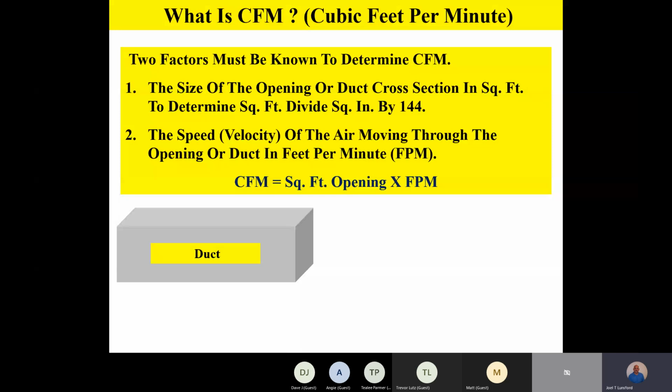A good way to do it is to have a manual damper on each. That way you can balance the airflow very nicely into each conditioned space. As you condition that space and commission the duct system, you can put the recommended CFM into each space, based on your airflow requirement. So on your branch ducts, we recommend a damper on each takeoff so that you can balance your airflow.